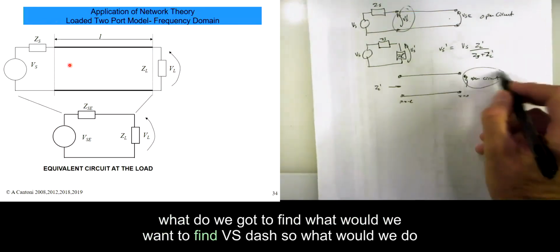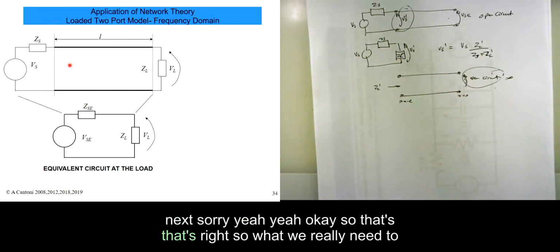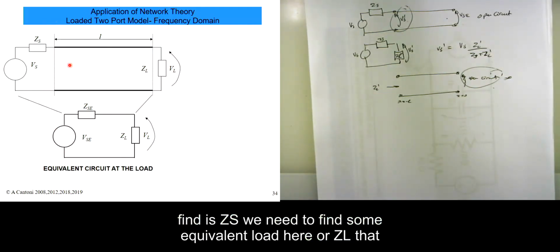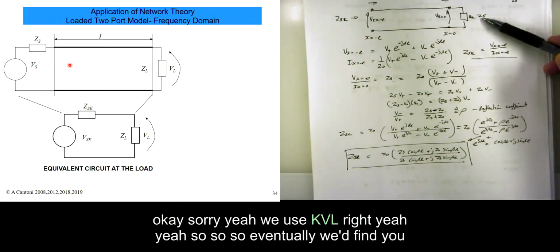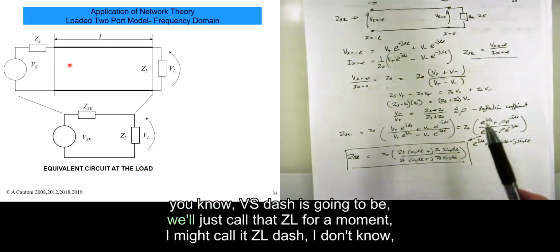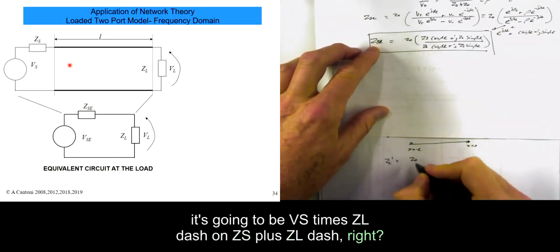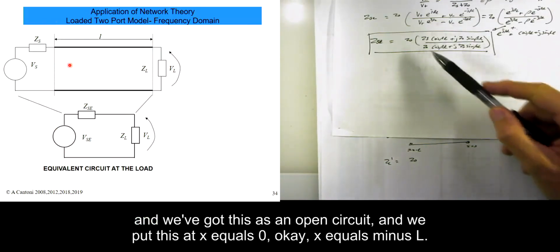So the first thing, to find VS dash, what do we have to find? What would we do next? Sorry? Yeah, that's right. So what we really need to find is ZS. We need to find some equivalent load here, or ZL, that corresponds to that open circuit piece of transmission line. Yeah, we use KVL, right? So eventually we'd find VS dash is going to be, we'll just call that ZL for the moment, I might call it ZL dash, it's going to be VS times ZL dash on ZS plus ZL dash, right? So we've got to find what that piece looks like looking in here, and this is an open circuit.